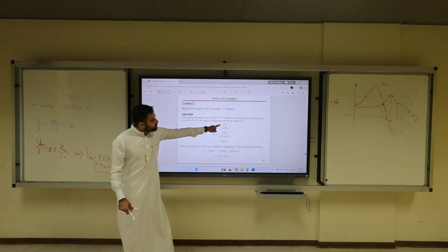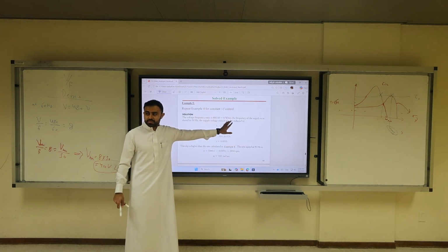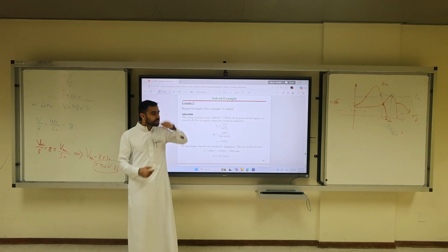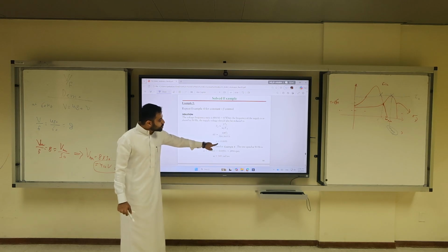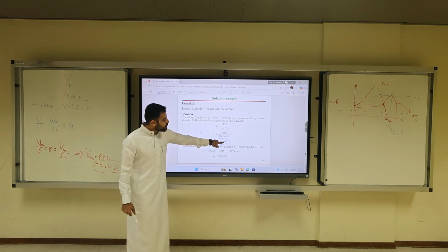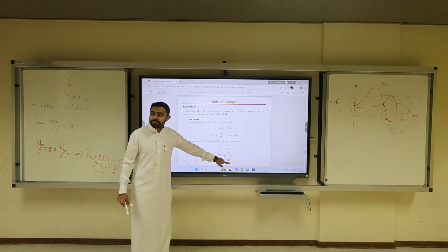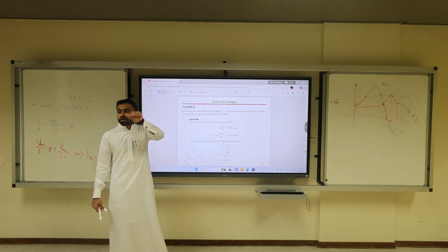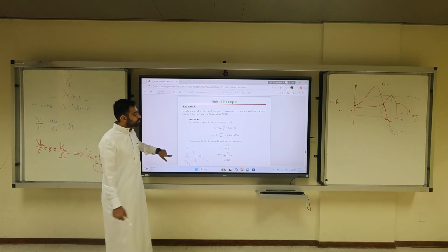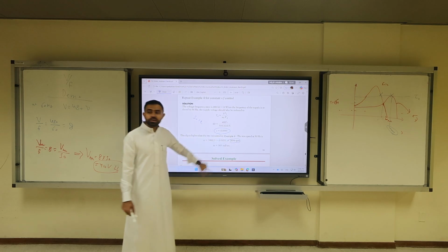Keep in mind, V over F is baked in as V over omega. It's inside. The ratio is inside. That keeps the torque alive. That keeps the torque at 60. So if you put the new numbers, you get a new slip at 50 hertz. Remember, this is 50 hertz. So your new slip is 3.53. What was your old slip? 2.45. So we have to increase the slip for lower frequency in V over F. So what is happening here is you get a speed of 2894 compared to 29 something.